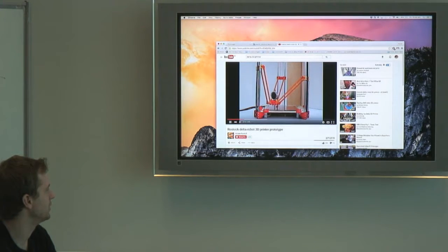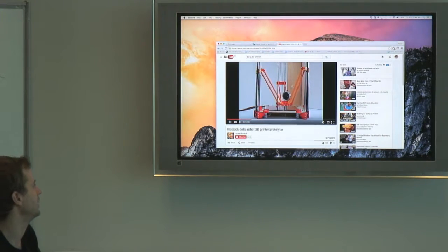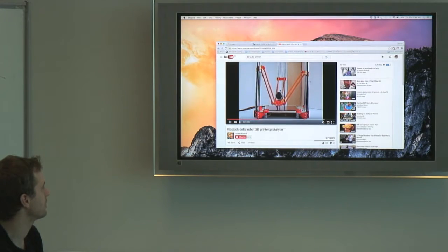The main advantage is it's generally slightly smaller than one with 3 big boxes, because the length of these arms defines the size of the build space, and there are fewer moving parts as well. So you have essentially these 3 things, and they control it in 3 dimensions rather than having rails and bearings running in 3 dimensions.